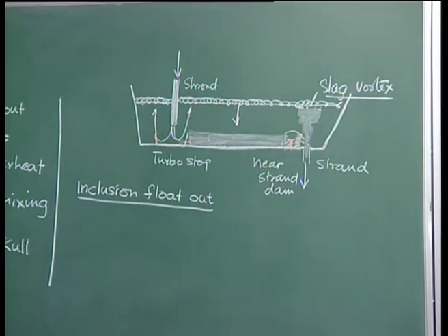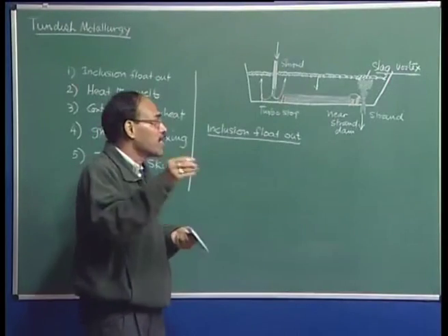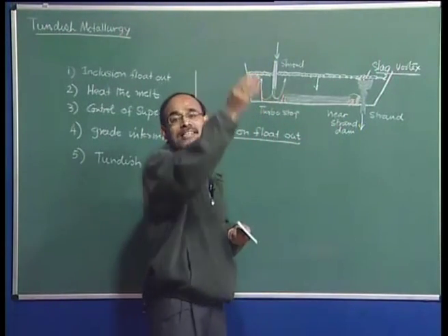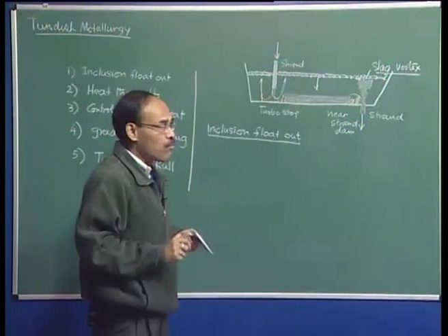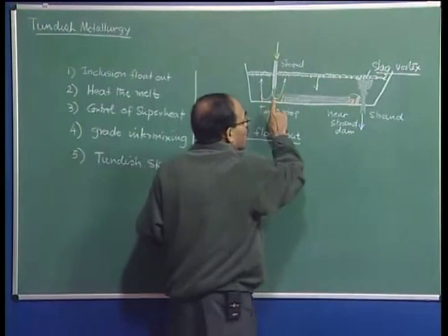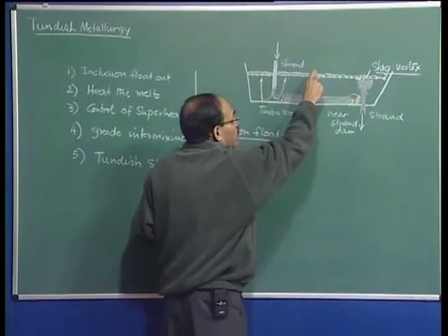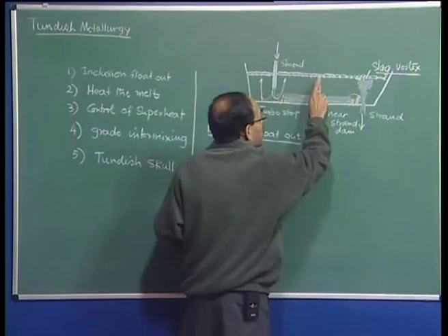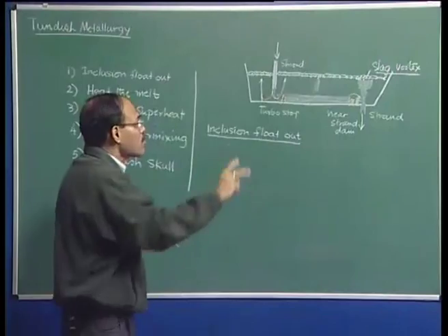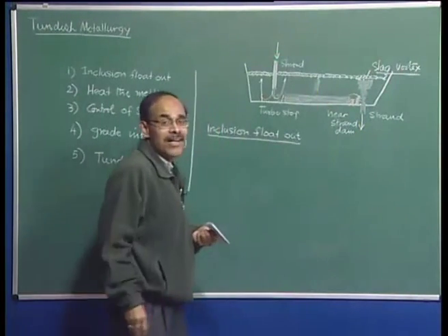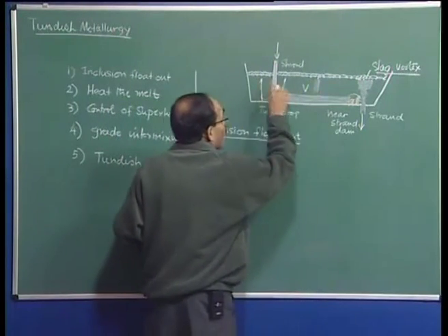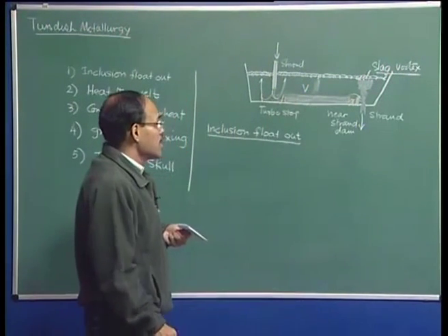Initially, when we fill the tundish, when there is nothing in the tundish but we are filling it up, okay, with nothing going out, the level of the metal goes up in the tundish itself. That is a transient mode of operation. Similarly, when nothing is coming into the tundish, and yet we continue casting, the level is going to go down. So, except for the lead heat, the first heat, or the last heat, most of the time the tundish is going to be operated under steady state bath condition, and at that point the volume of the tundish occupied by molten steel is going to be constant.